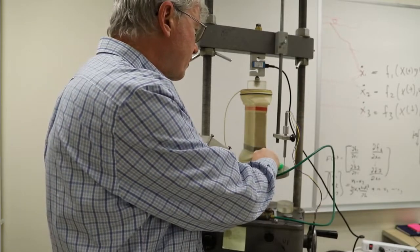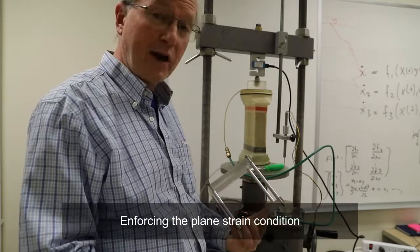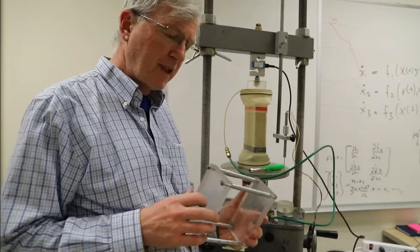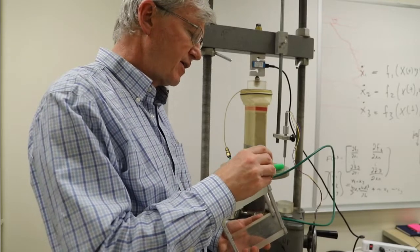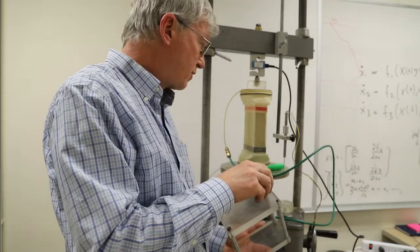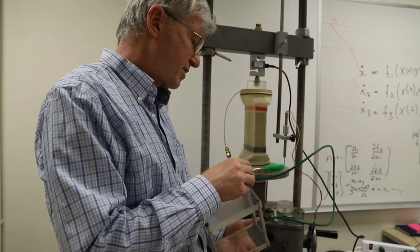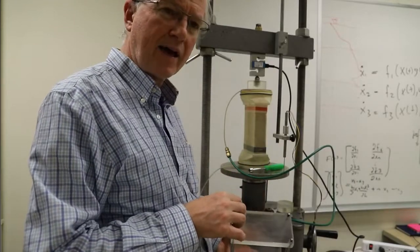But there's one more very important feature in a plane strain test, and that is how do we enforce those conditions of plane strain. And that's what we need. This system has 2 rigid platens and 4 tie rods that hold them together. We're going to put those across the small vertical surfaces to prevent the sample from straining in that lateral direction.